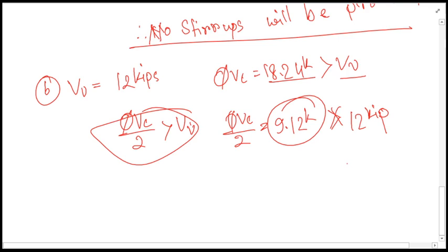And how will we be providing shear reinforcement? As you know, in the case of shear reinforcement, we don't actually determine the area of the shear reinforcement; rather we determine the spacing after defining one particular number of reinforcement. So for spacing, there is a guideline. We have the guideline for S max.